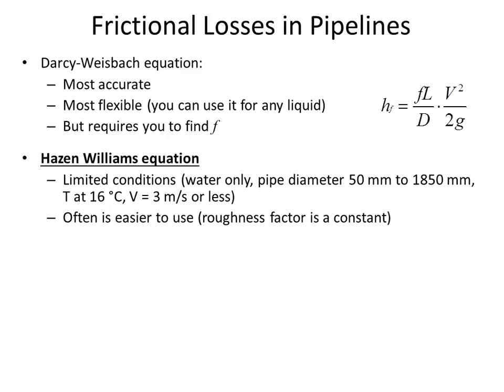Another interesting fact is that the Hazen and Williams equation was derived for sort of room temperature water, 16 degrees Celsius. And so when water is very warm, there are mistakes with the Hazen and Williams equation, and also when water is cold. Water flows through pipes underground at about 55 degrees Fahrenheit, which is going to be less than 16 Celsius.